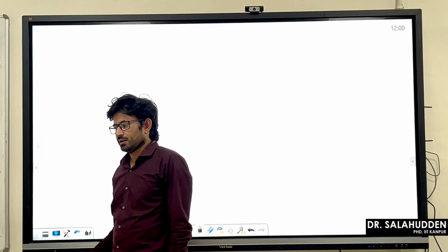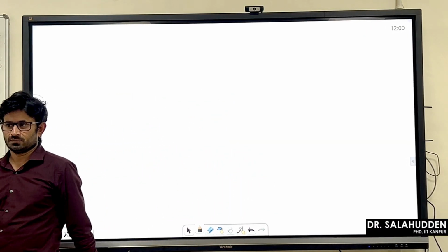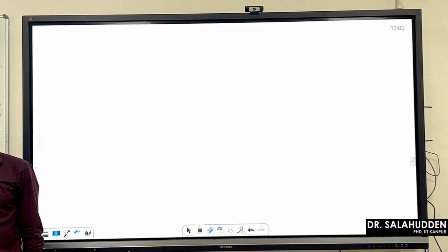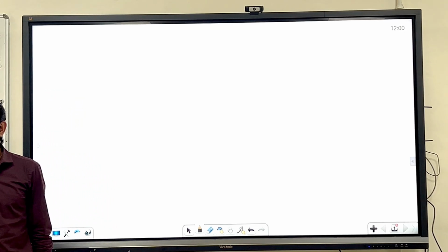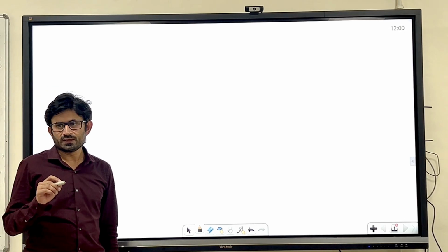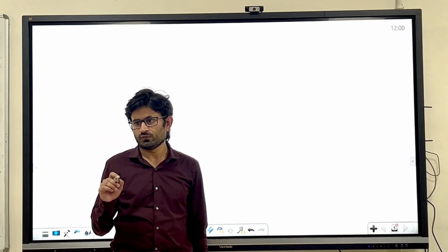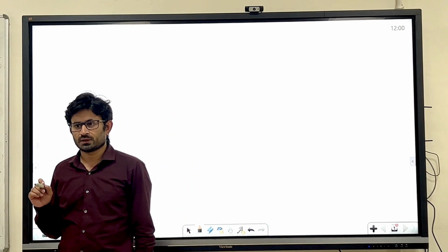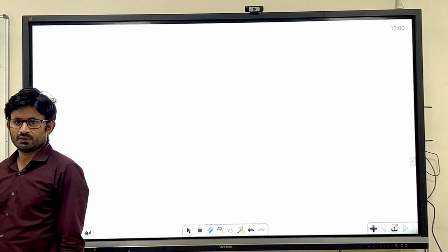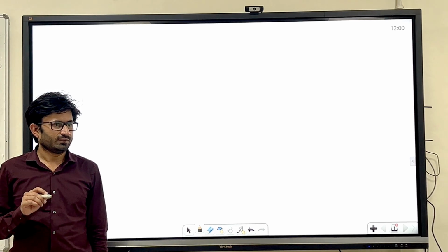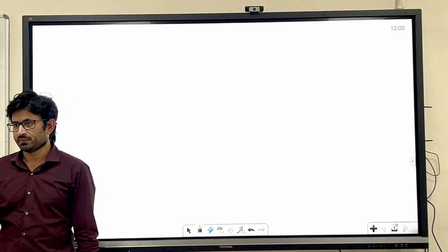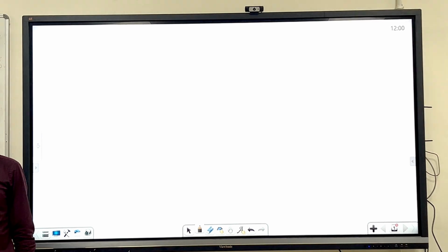Hi everyone. We have done with the weight estimation part. What was the weight? Approximately 1237 kg, right? To lift that weight, we have sized the wing, where the root chord, tip chord, span, area, aspect ratio, everything we have finalized at a preliminary stage, not the final stage.